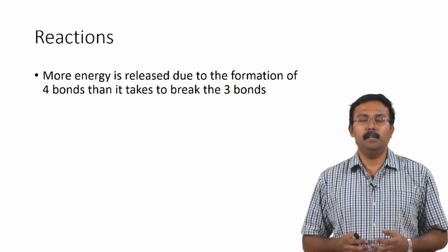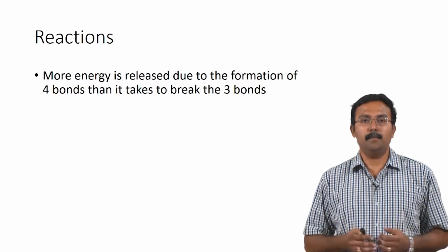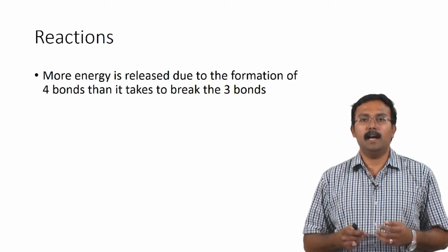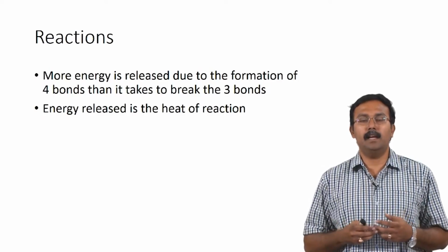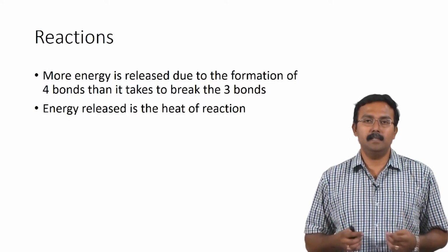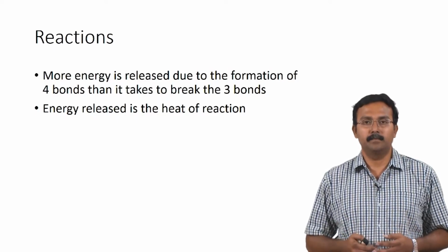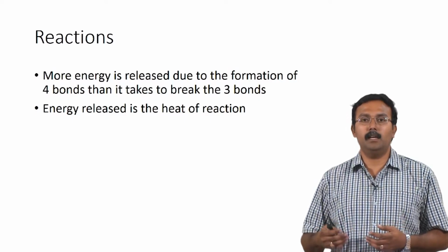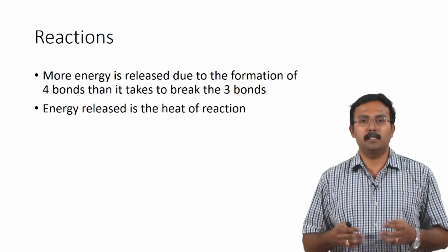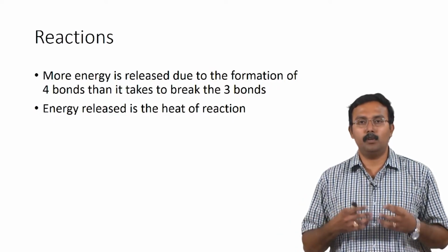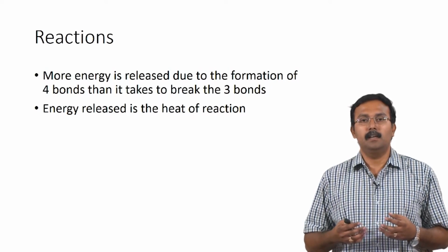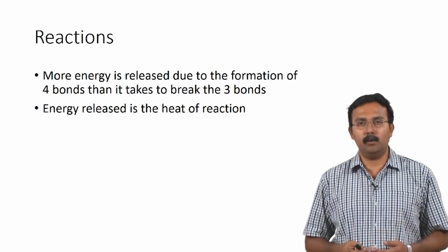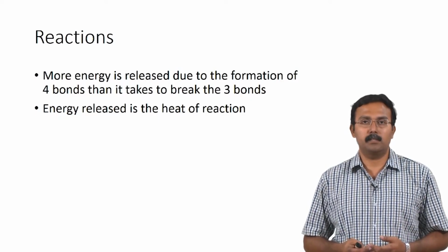So, why do we need to look at energy balances? What happens is when more energy is released due to the formation of 4 bonds than it takes to break 3 bonds, you would have energy being released, and this energy which is released is called the heat of the reaction. If it is the other way, where the amount of energy released during the formation of 4 bonds is lesser than the amount of energy required to break the 3 bonds, then energy will be absorbed and that would also be the heat of the reaction, and this needs to be accounted for while you perform energy balance calculations.